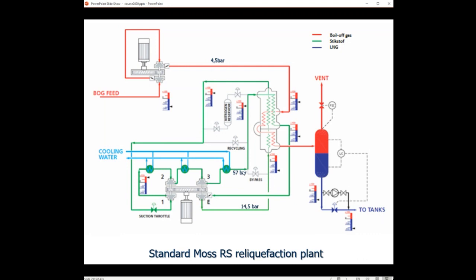But of course, you'll need to go to much higher pressures. Compared to 57 bar, for the LPG compression you go up to pressures of 12 bar, depending a little bit on the product you are carrying. For ammonia, something like 10, and propylene might be a bit higher, 12, 13 bar. But here for LNG, you need to go up to 57 bar. That's quite high.